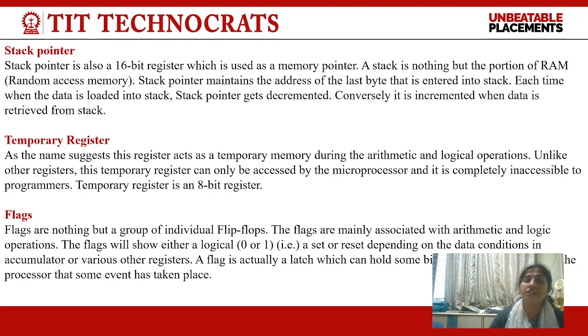Stack pointer: a stack means what? Aligning things one above the other is known as stacking. So the stack pointer does the work similarly. It is a 16-bit register which is used as a memory pointer. A stack is nothing but a portion of RAM, that is random access memory. The stack pointer maintains the address of the last byte that is entered into the stack. Each time when data is loaded into the stack, the stack pointer gets decremented.